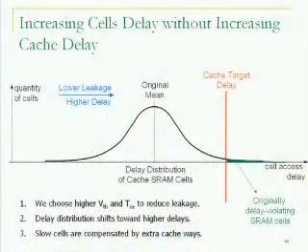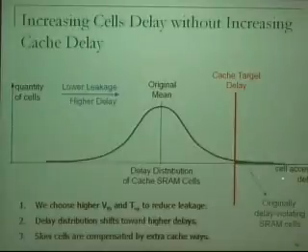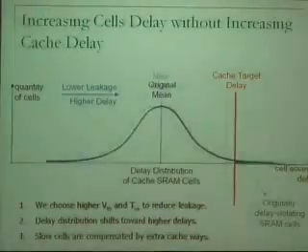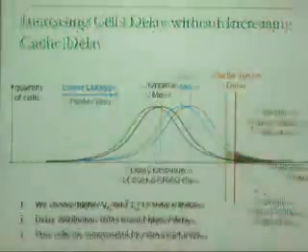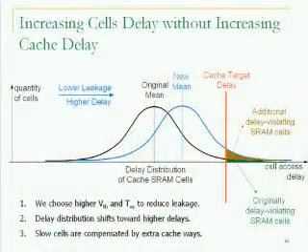In terms of showing that in a figure, it can be viewed like this. This is the SRAM delay distribution. We turn the knob, so the delay distribution moves like this. So some additional delay-violating SRAM cells appear here. And we take care of this number, assuming that this delay distribution follows a Gaussian distribution.